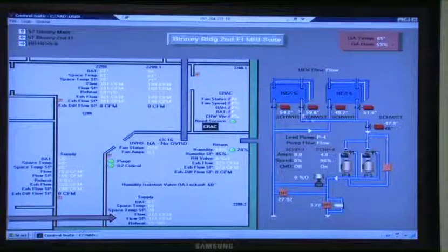And then secondary comes off this and serves medical grade, clean, processed chilled water going down to this MRI and an MRI up on 7. Okay? So it's a dual system. It has pumps, differential pressure valves, DP set points and sensors going through, and all this kind of business here. This is just a quick reference to let you guys know where that comes from.